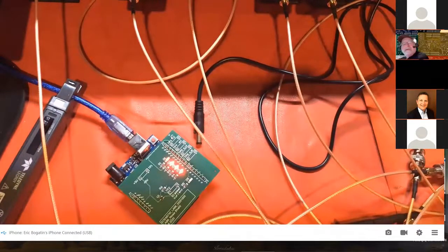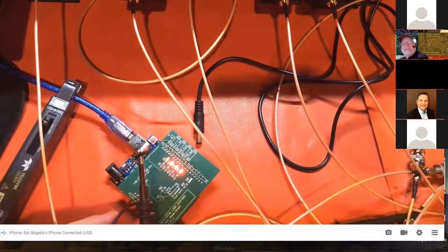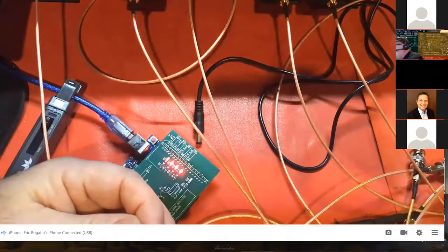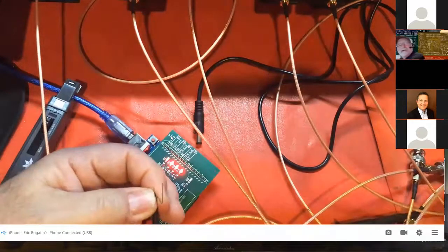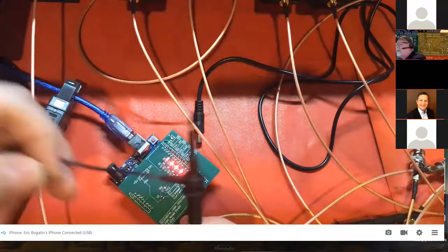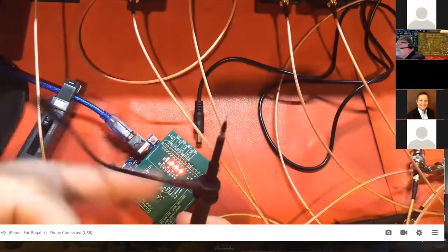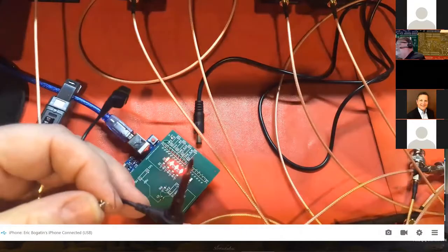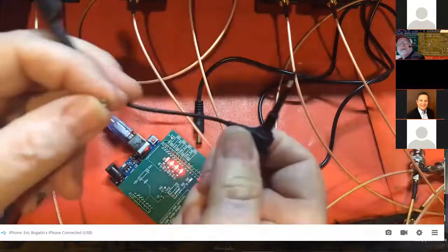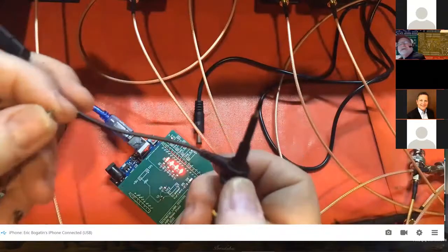Okay, so here is the 10X probe. Now, in this 10X probe, I pulled the cap off, and there's this little spring end that just kind of unwinds, and I've still got the long ground lead connected here. If you plan to do a lot of measurements of the spring tip, the tip unscrews, and you can pull off the ground lead. Otherwise, who cares, it just flops there.